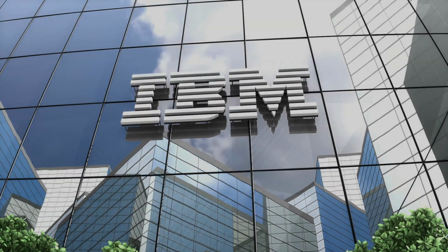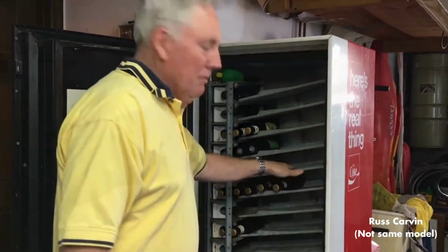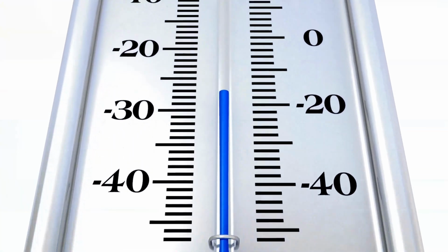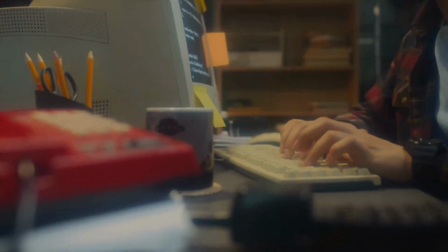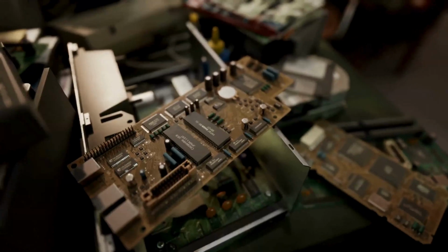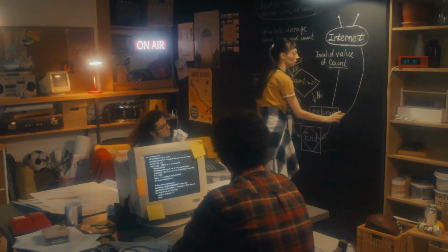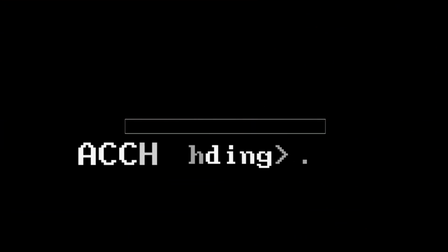According to IBM's Industrious blog, students installed micro switches in the bottle-based vending machine to keep track of the fill state of each column. They also tracked how long the bottles had been inside the 1970s machine. To determine whether drinks were cold enough, they installed temperature sensors. The most innovative part involved connecting the machine to the university's network. Students designed a board that interfaced with the machine's sensors and connected to a computer. Custom-developed software queried the connected computer for the machine's status. Using it, you could send a simple command from any terminal in the network, and the program would return info about the drink situation.